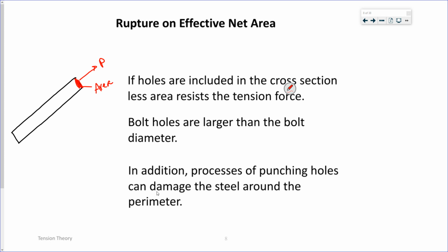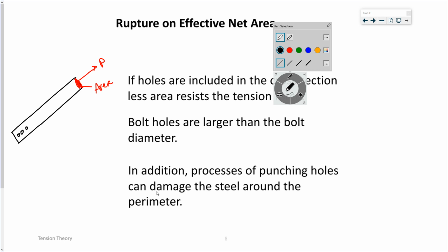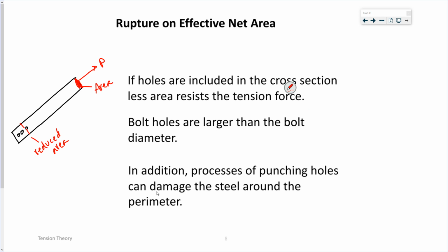Now, if I punch some holes in it for my bolts, I've now reduced that cross-sectional area. So there's less area to resist that tensile force.